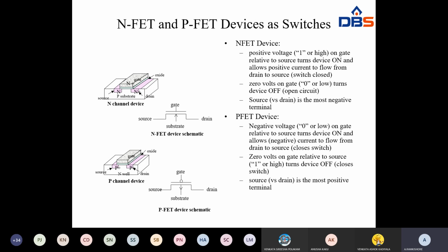So here such a circuit may interpret any voltage in the range of 0 to 1.5 volts as a logic 0, and in the range 3.5 volts to 5 volts as a logic 1. Voltages in the intermediate range are not expected to occur except during the signal transitions, and it creates undefined logic values. So this is about the introduction of CMOS logic.